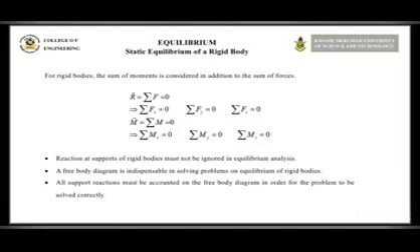On your screen are the equilibrium conditions. The resultant force R is equal to the total forces, that is, forces on the x-axis, forces on the y-axis, and forces on the z-axis if it is in 3D. The total moment is equal to the total moment about the x-axis, y-axis, and z-axis. It comes in handy if it is in 3D. So in 2D, you use the useful ones.